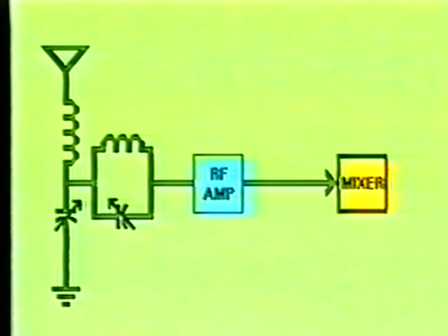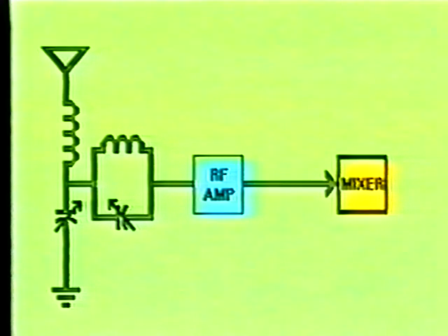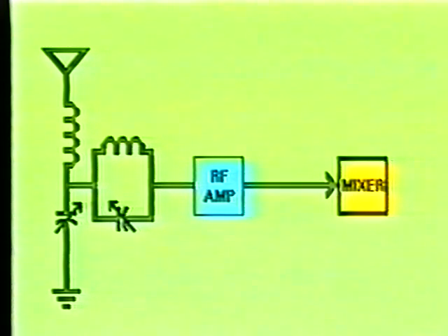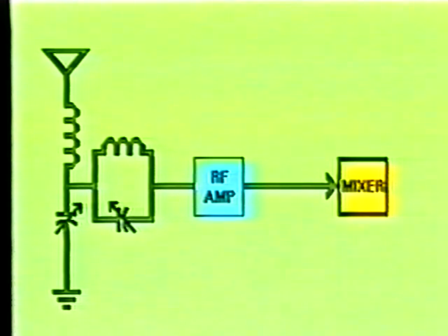Due to its inherent characteristics, the mixer stage will typically generate large amounts of electrical noise. Therefore, by amplifying the weak RF signal, the signal-to-noise ratio is greatly increased. The signal-to-noise ratio is a relation of signal power to noise power within the given circuit. Since most of the stages following the mixer stage will amplify the noise being generated by the mixer stage, the RF amplifier almost becomes a necessity for distant stations.